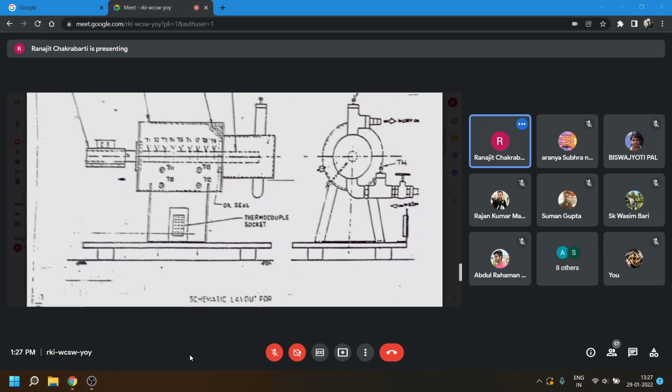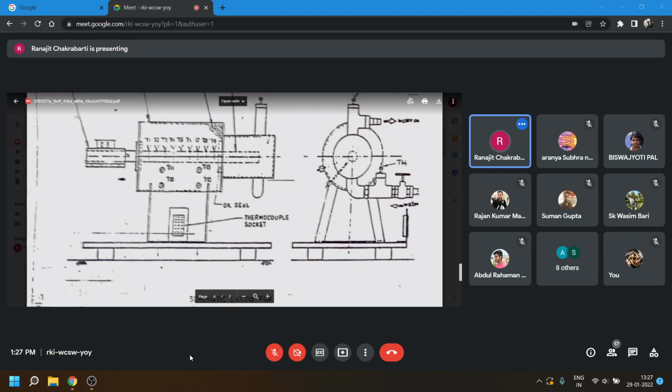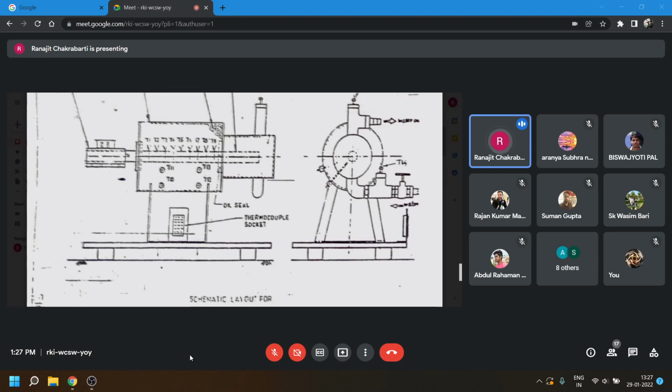And this heat is flowing only in the x direction, that is the z direction, you can say. That is the length of the rod. In the other directions, that is the radial direction or any angular direction, there is no heat transfer. Consider the cylindrical coordinate system. In the cylindrical coordinate system, one coordinate is the axial coordinate of the cylinder. Here also, that is the coordinate along which the heat transfer occurs.